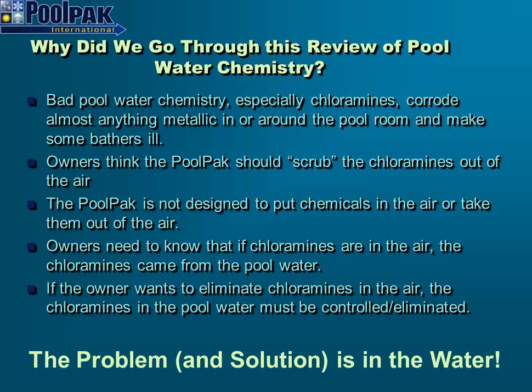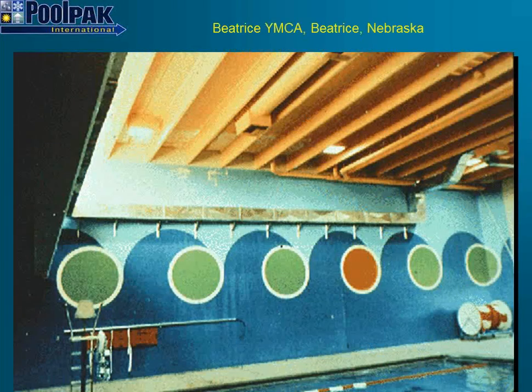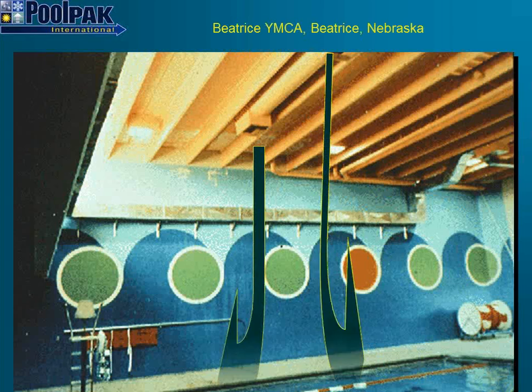Now, air distribution. Sometimes we'll be going into a replacement situation, but certainly we'll be getting into other jobs where new pool structures are going to be constructed. Air distribution in a replacement situation is kind of an old school treatment of a pool natatorium. Sometimes the ductwork was put right over the pool, and here we have a situation where we're blowing dehumidified air right onto the surface of the water and reabsorbing water. That's not what we want to do.